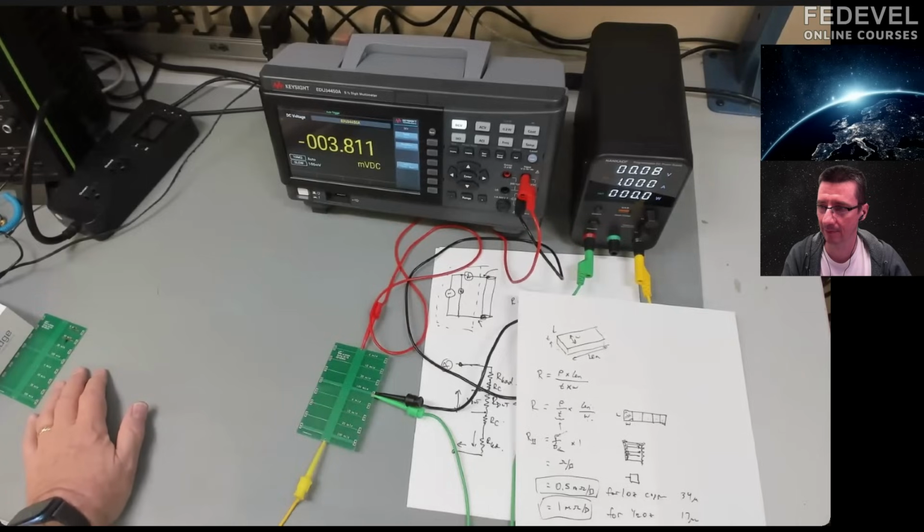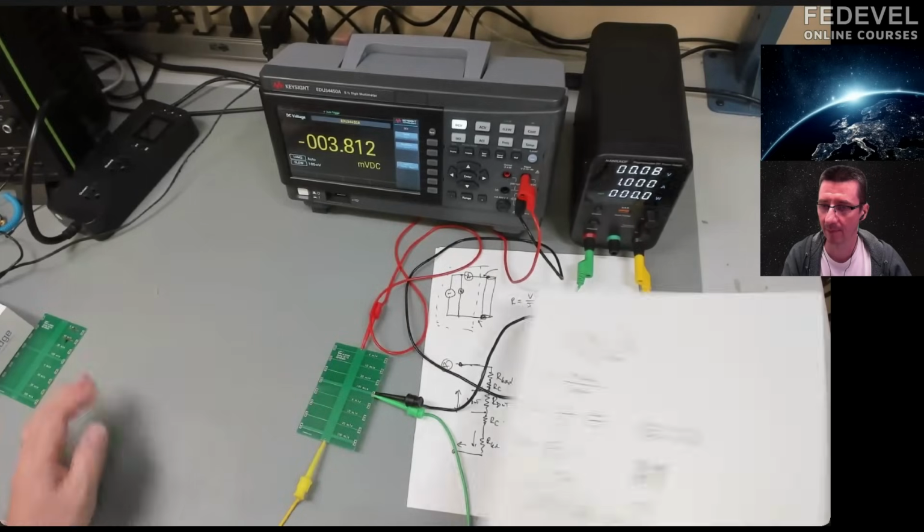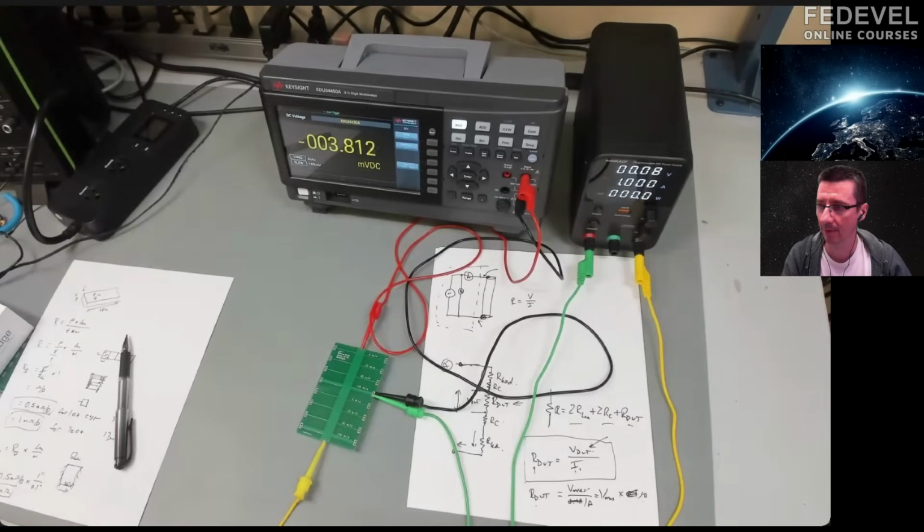So it's probably 1 ounce with the plating. I don't know what the thickness is, but I think it's thicker than 1 ounce copper, and that would pull the resistance down. So this value of 3.8 milliohms for the 100 squares is probably a good number.